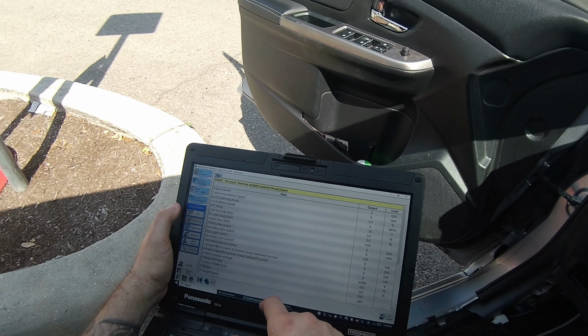Okay, we have no flashing ATF light. Gotta step on the brake. There's my code. Now we got a current set condition. And good, that's what I want. I want 3 iterations of freeze frame. This is better. Okay, so the ATF is not related. I wanted to do that because in the other freeze frame, it showed that the control module voltage was 0. So obviously, if that sensor has no voltage going through it, or if the computer's unplugged, it's going to read negative 58. So let's not go down that rabbit hole.